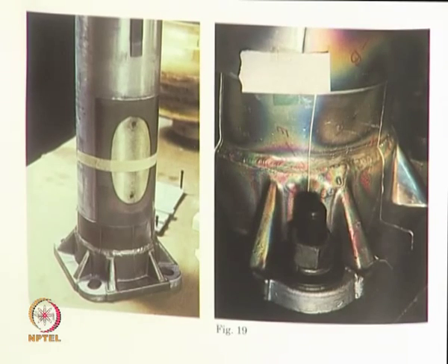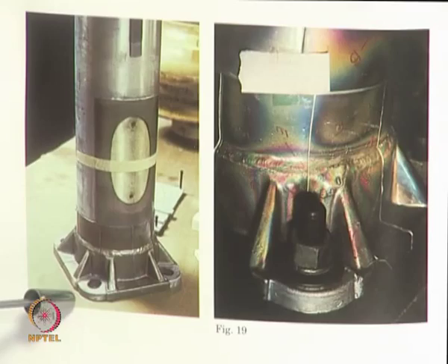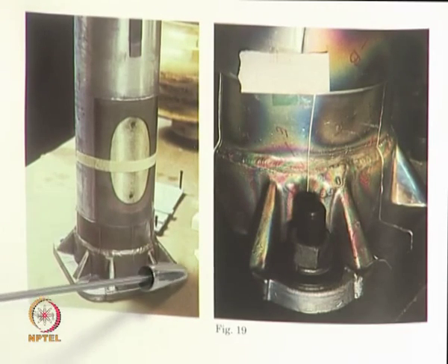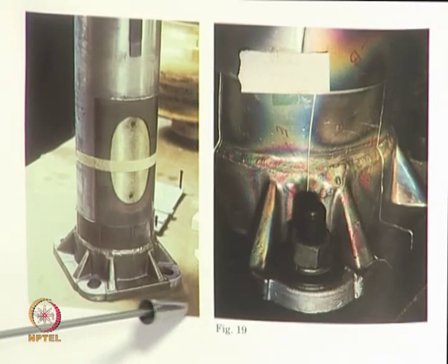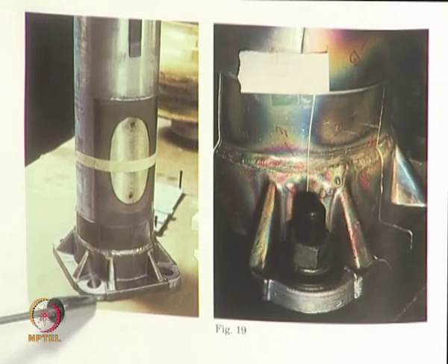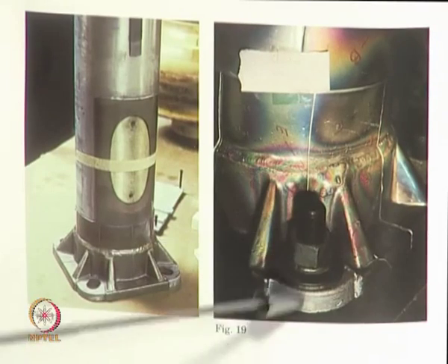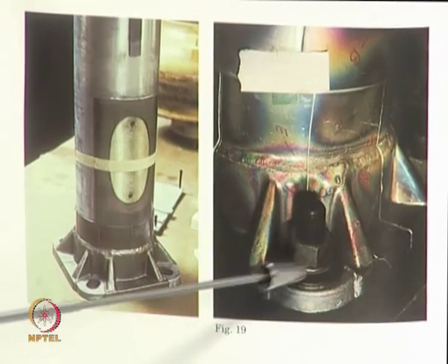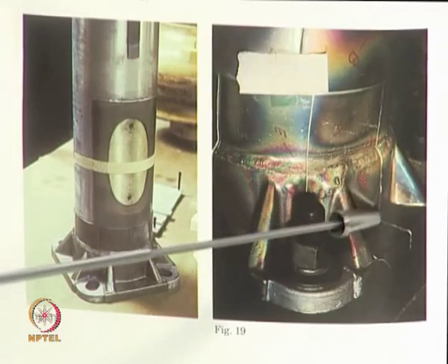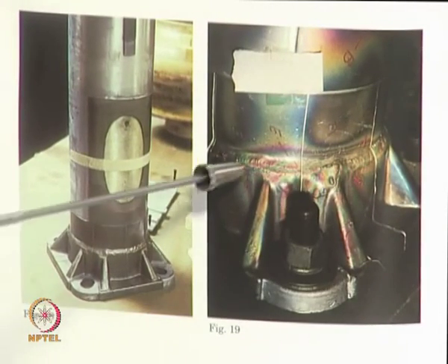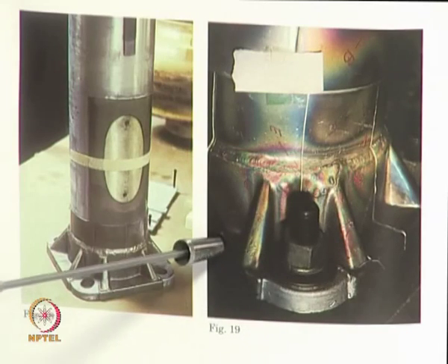This is an example which shows how photoelastic coating is useful for studying assembly stresses, and this is the mast that is used for street lighting, and you have here it is tightened. After tightening with the bolt, it has developed rich colors indicating a very high value of stresses because of assembly.